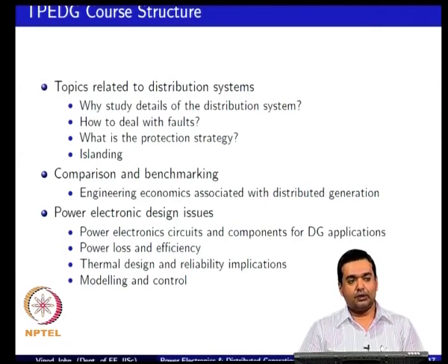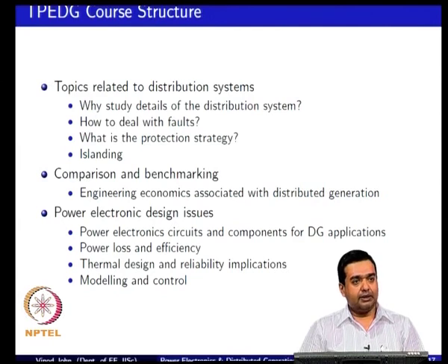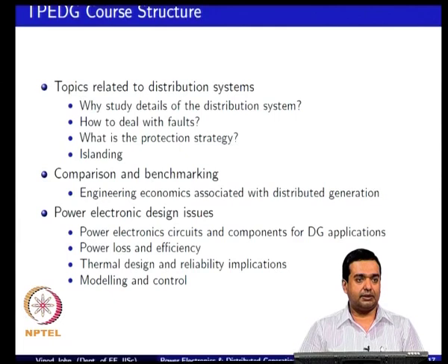So, the question is what sort of inductors, what sort of capacitors, how do you rate them, how do you size them, what sort of semiconductors, how do you rate them and size them should go into such an equipment. There are implications of the selection in terms of both efficiency and reliability, and ideally there is no loss in an inductor, capacitor or switch, but you always have non-idealities in a practical circuit.